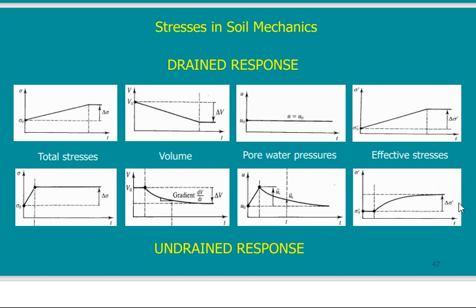And the effective stress, this one, actually we are keen to know what this is, because when we come to design our foundation, we use the effective stress. So maybe here it is not a big problem, but here it is a big problem because this value of T may be years. So imagine you want to design a building that is safe now in the case of total stresses, and it will be safe maybe 2 years later when all the water is expelled and the effective stress reaches a different value.